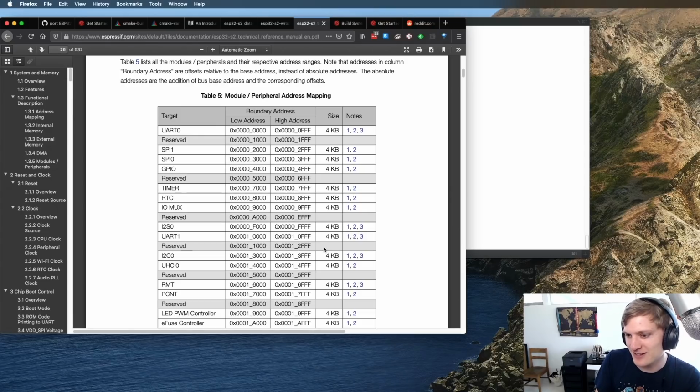Yeah, speculative reads. There was a bug that Damien was telling me about on the STM32H7s as well, because they speculatively fetch as well. And he had an issue where after hours of running SSL stuff, he would end up hard locking, where the debugger would die, like nothing would work again. And it took him like a month, not because he's not smart, he's super smart, but because it's just so random.